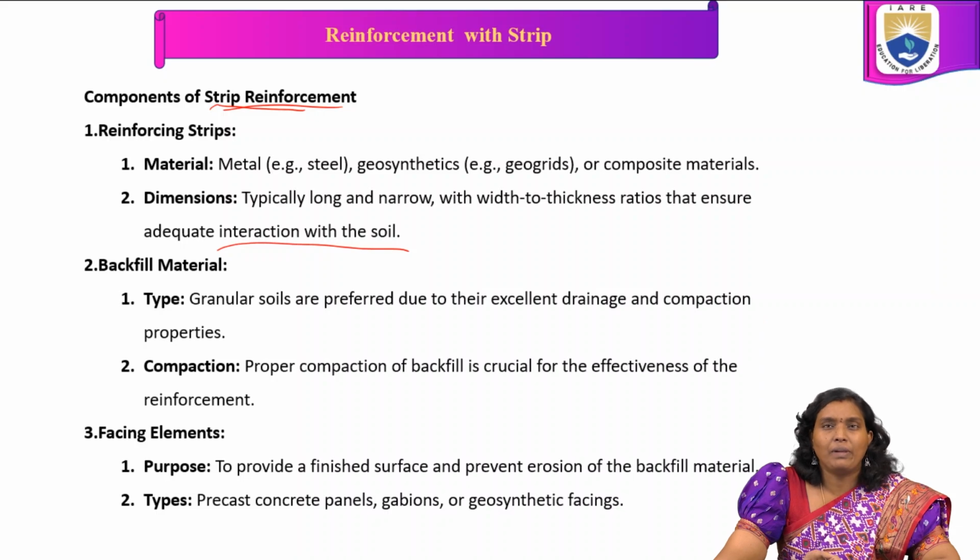As a backfill material, granular soils are preferred due to their excellent drainage and compaction properties. Proper compaction of backfill is crucial for the effectiveness of the reinforcement.